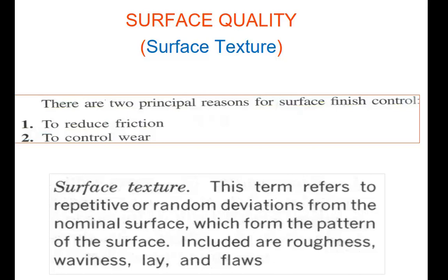During the solidification stage, the sand particles over the surface of the template just set a certain pattern over the surface of the object. Depending on the size of the sand particles in the structure of the template, we have a certain irregularity over the surface of the object. These are set by the sand particles during the solidification stage.